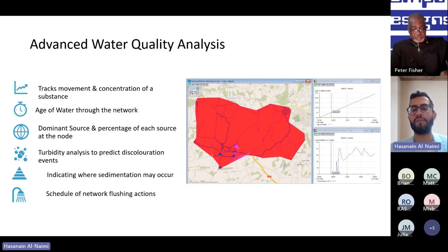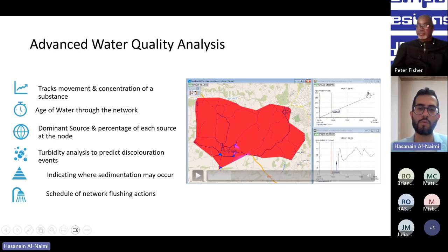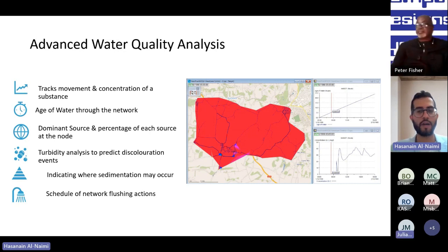But if you want to automate it, then the software will take that result and use it as the boundary condition to run the new simulation. You know what I mean? And you're able to set it at a predefined frequency. So you tell it every 2 hours, I want you to connect to the SCADA and run that simulation, or every 5 hours, or every day. So you have the ability to do it like this.